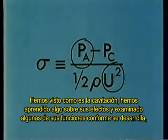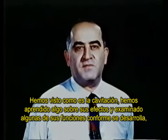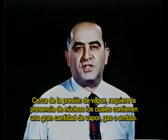We have seen what cavitation looks like, have learned about some of its effects, and examined some of its features as it develops. Pressures near the vapor pressure require the presence of nuclei, which contain minute amounts of vapor, gas, or both. Cavitation will occur only when these nuclei become unstable and grow when subjected to a pressure reduction. The conditions for such growth can be derived from an analysis of the static equilibrium conditions for a spherical nucleus.